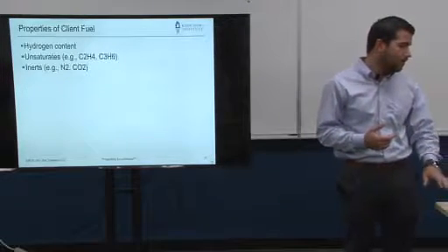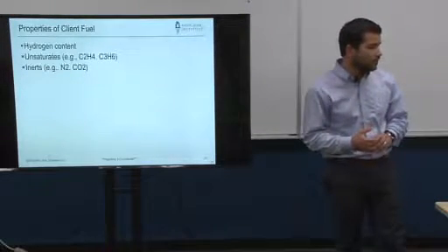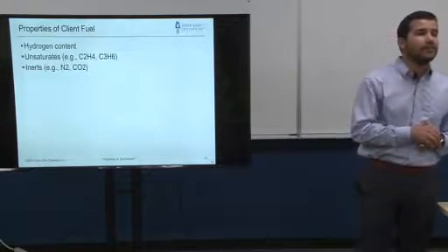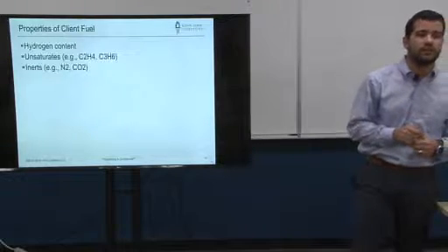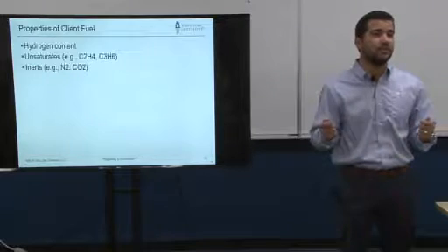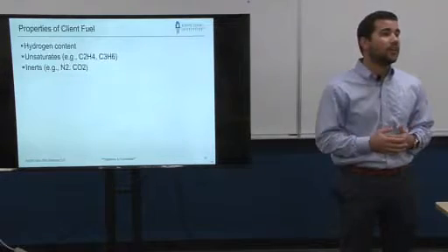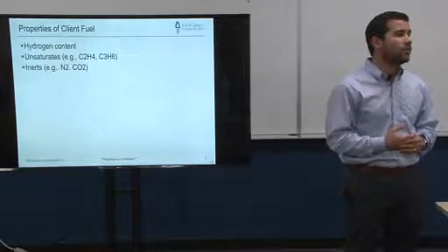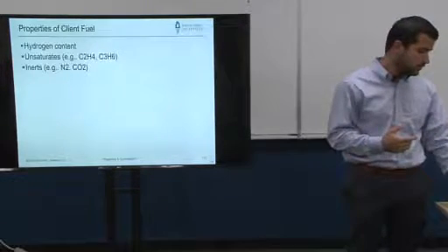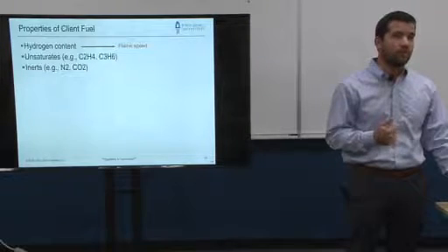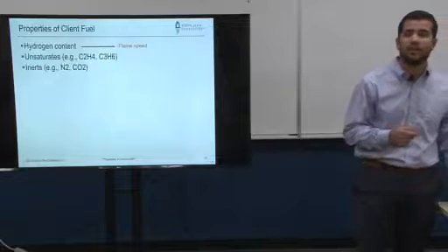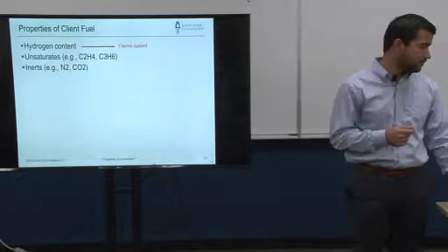And there are a couple of things that we look at. One of them is we look at the hydrogen content. Hydrogen content is one of the first things that we're trying to match in our fuel composition, simply because hydrogen has a unique capability of burning really fast and burning really hot. So when it does that, it brings questions in regards to emissions, right? So that flame temperature is what we're looking to replicate, and really there is no other fuel that'll give you that same really fast flame.